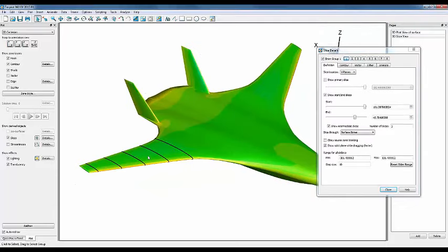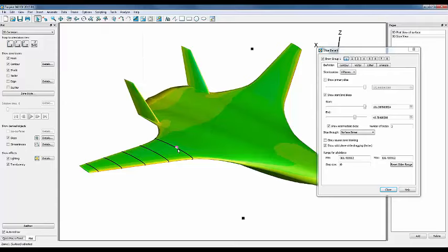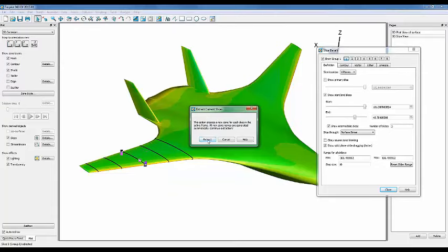In the past, if I wanted to slice a surface like this, I would have had to do this by a macro. If I wanted to extract, say, CP at these slices, I would have done a data extraction. Today, you still can go current slices. In this case, it's going to extract the surface slices. Or perhaps more conveniently, if you select one of the slices and right-click, if you right-click on the actual slice group, it tells you slice group 1, and you can do a hide or extract. So in this case, ultimately, you want to extract. So if I hit extract, it's going to extract all of the slices.